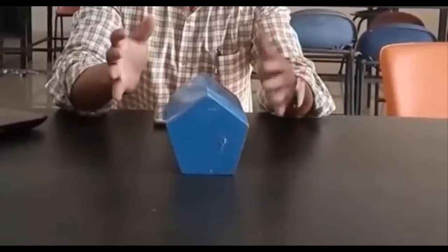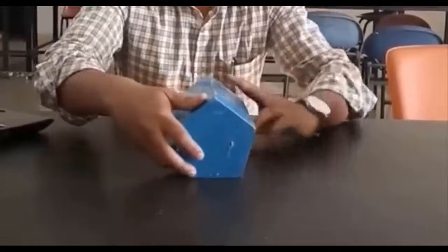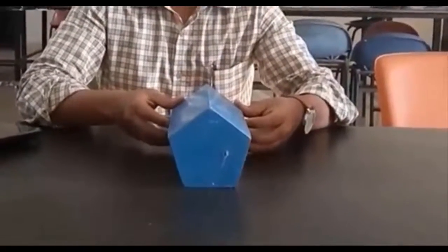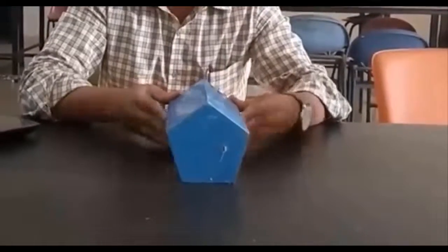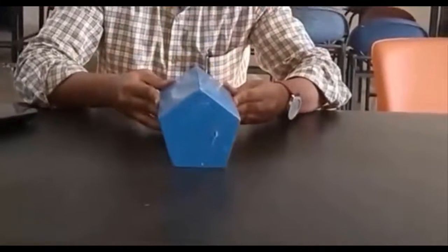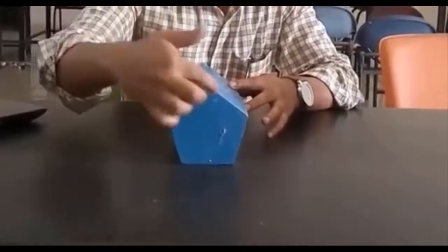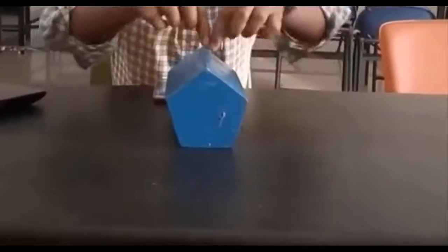Alright, so the pentagonal prism has to be oriented in this manner, and at the same time we need to ensure that the axis starting from this point to this point over here should be kept at an angle of 45 degrees with the vertical plane. So what we need to do is, this is going to be our step number 1. Alright, and the true shape of this base can be seen from the top, and hence you have to begin by drawing this front view first, and then accordingly its top view can be made.